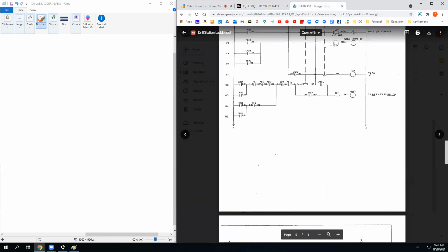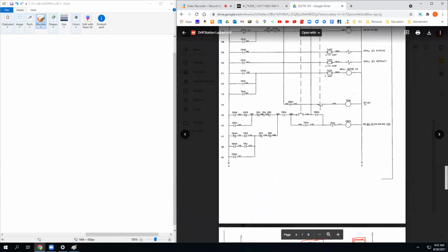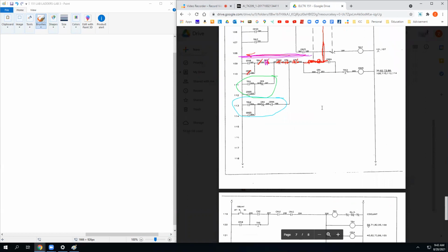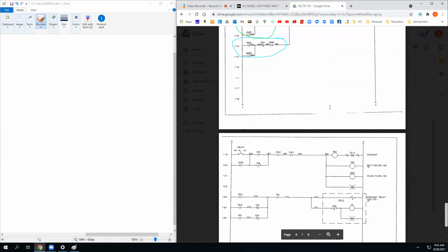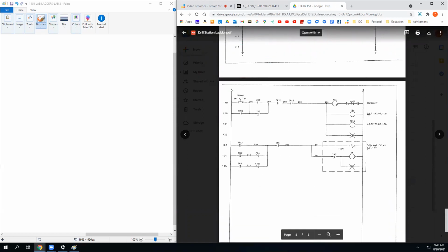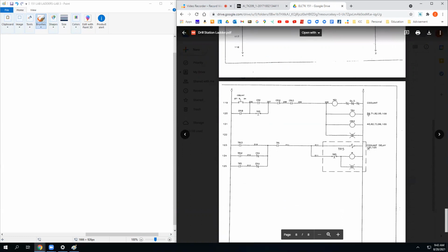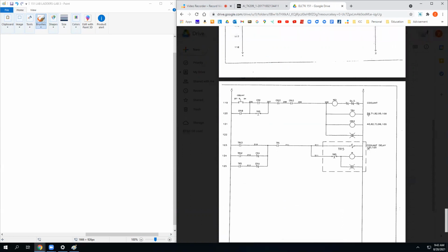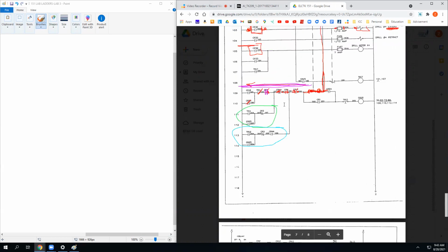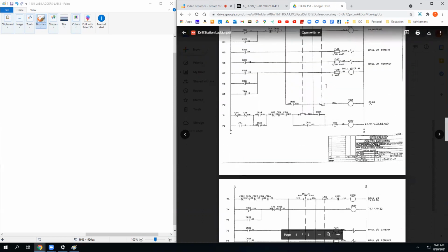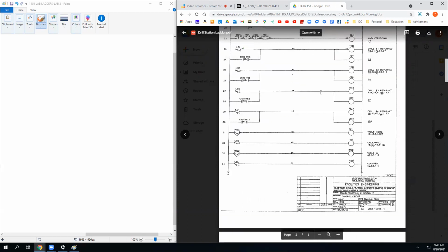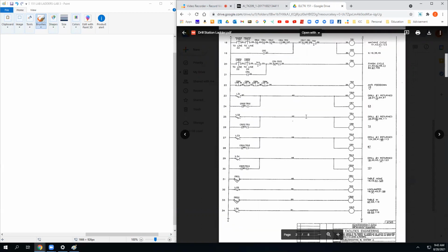But in this example, and I just showed you, you're going to see this too. You might find the output that is the coolant. The coolant's not turning on. Okay, let's check this motor starter. CR13, oh, we've got a problem here. This CR12 is not closed, and it should be. So where's CR12? It is on page 2, and we were just on page 8.